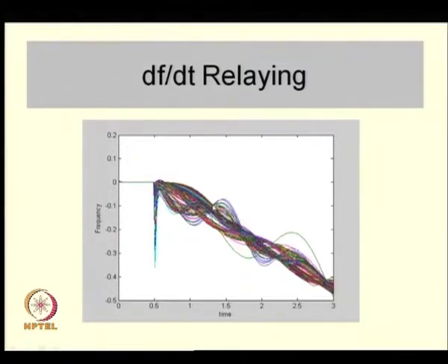You will see that not only is there a common motion, there are also these swings. And interestingly, there are many swings. You see one relatively low frequency swing here, then a higher frequency swing here. So, there seems to be a mixture of swings superimposed with the center of inertia or the common motion of this system.